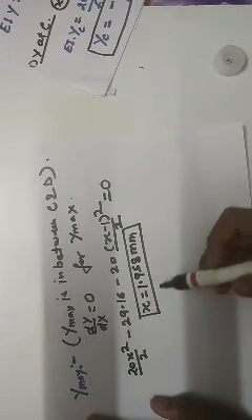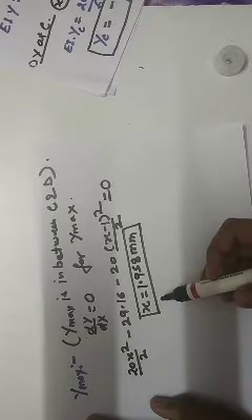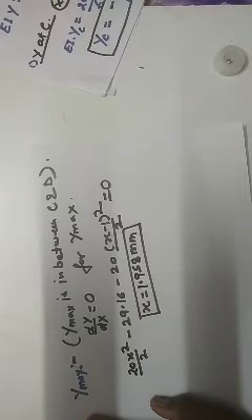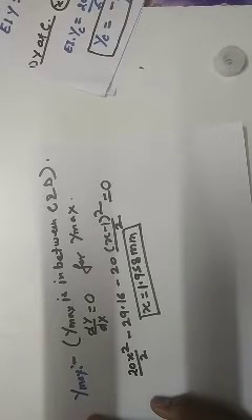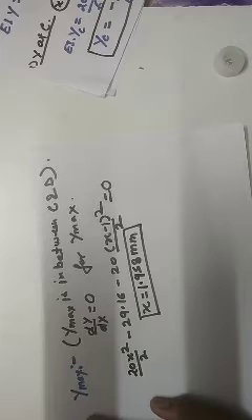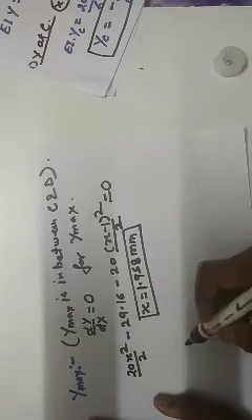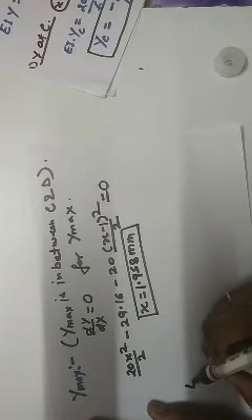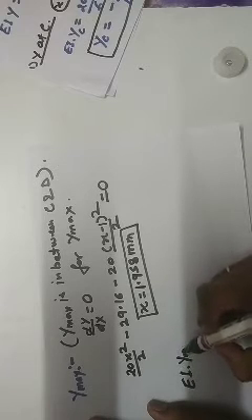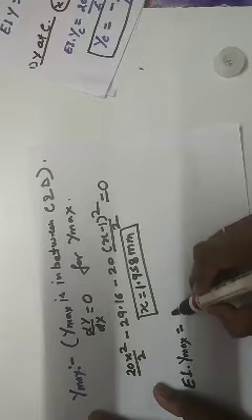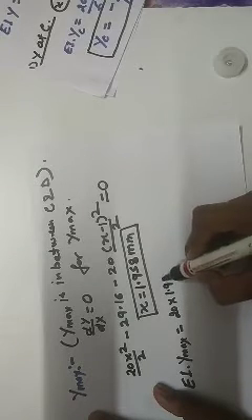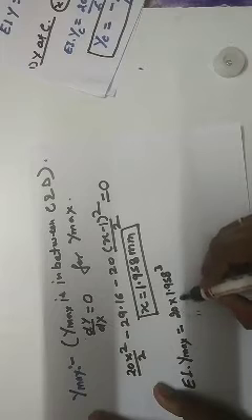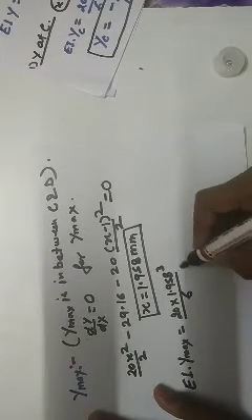Clear? Now at this value, we will calculate the maximum deflection. Right? What are we finding? At x equal to 2, the deflection at C was 8.74, right? And for the value of x less than 2, there the maximum deflection is happening. Let's find out the value, right? Then the value at this point will be EI y max. Put this value into the deflection equation. EI y max equals 20 into 1.958 cube upon 6, right? Minus